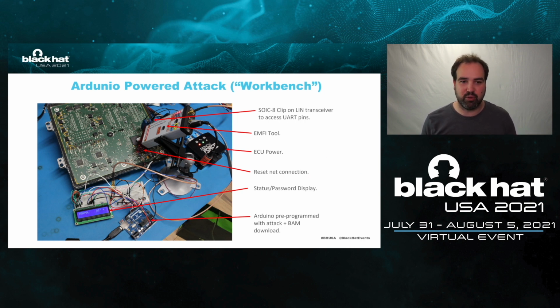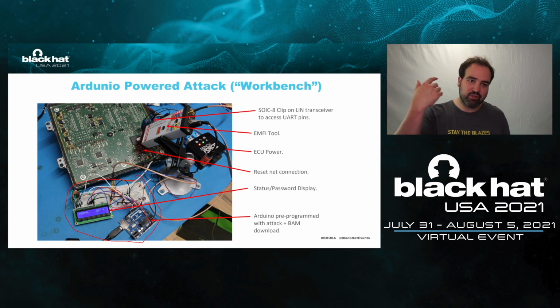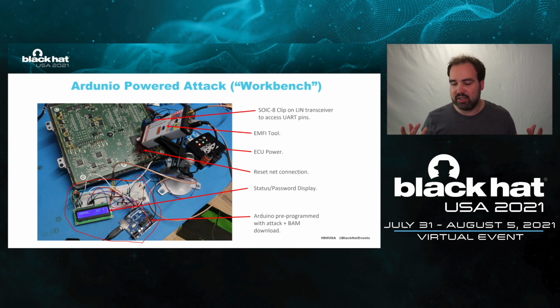The most expensive part, of course, is the EMFI tool. There are open source and other EMFI tools like BadFET that have been presented, and there's a few different ones now. So that's by far the most expensive part, not the controller. The controller doesn't have to be very complicated, so I use an Arduino. It understands that bootloader protocol I showed you. It can talk to the ECU, send a password, and generate a pulse to trigger the EMFI. The timing wasn't super specific, so it would actually work really well. It can give you some feedback, and when it successfully executes, it reads the password back as it's printed out.